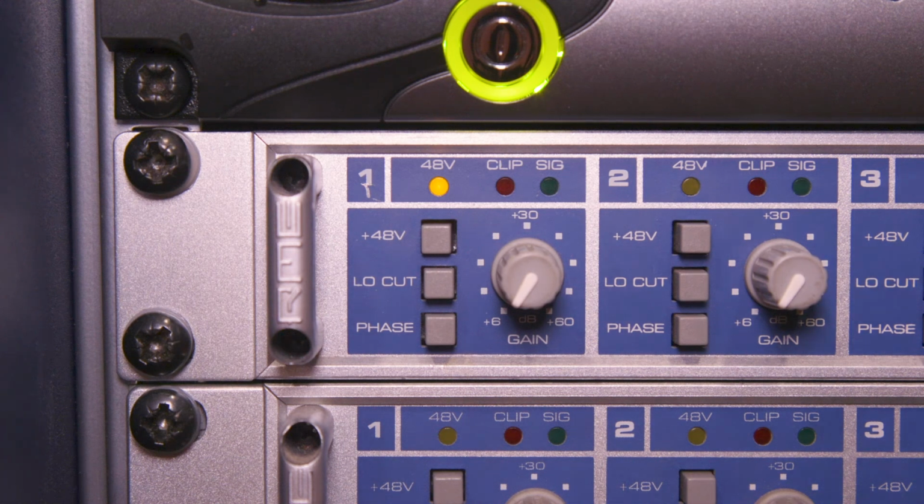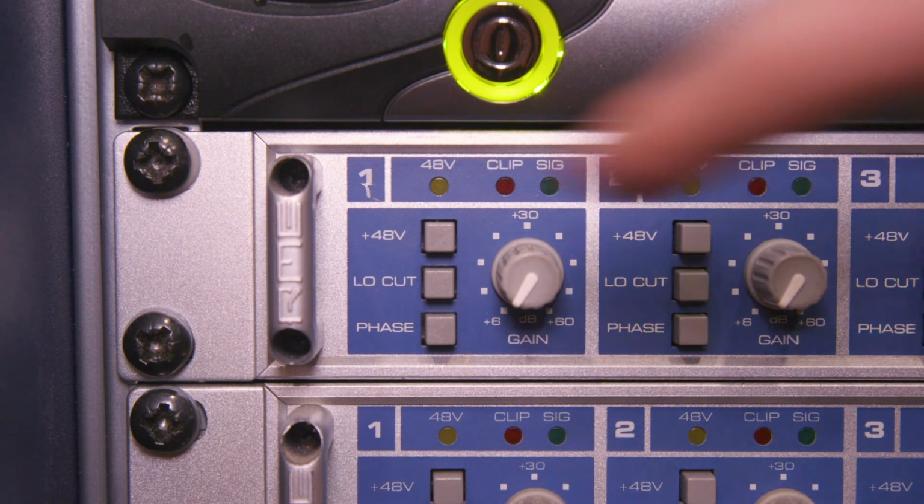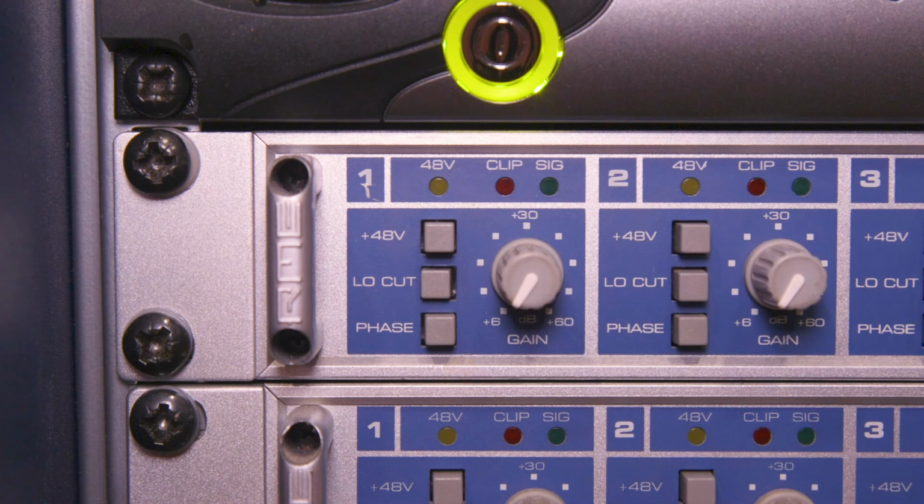The low cut button, also known as a high-pass filter, removes the lower end of the frequency spectrum from the signal. Usually this is set to cut anything below 80 to 120 Hz. This is useful for cutting out low rumbles or foot tapping on higher instruments like vocals, strings, or woodwind. However, if used in conjunction with an instrument with a lot of low end, such as a kick drum or a bass guitar, it may seriously and permanently compromise the recorded sound. You can always apply a low cut in a mix, so if in doubt, don't engage this button.